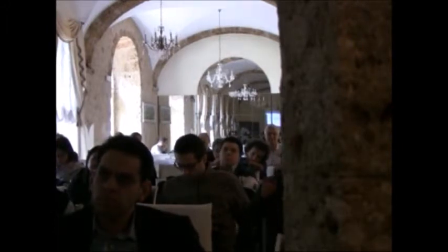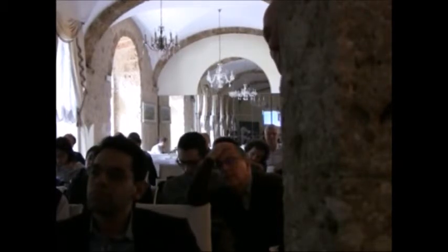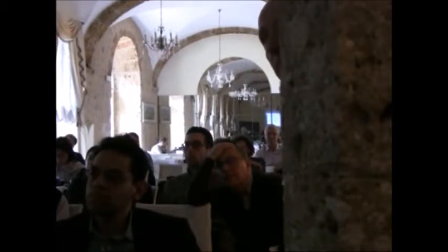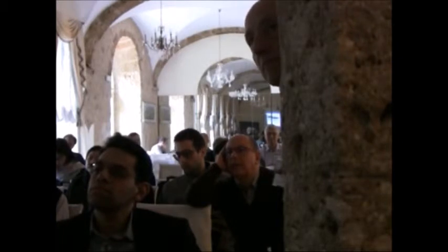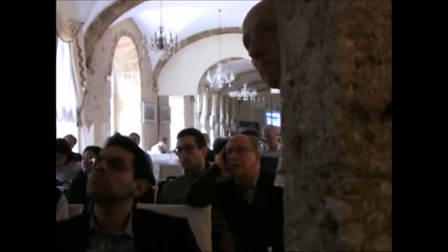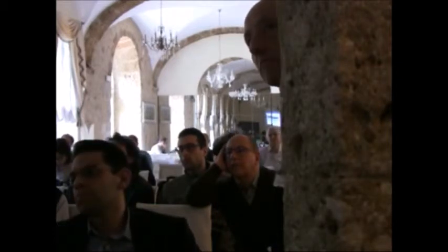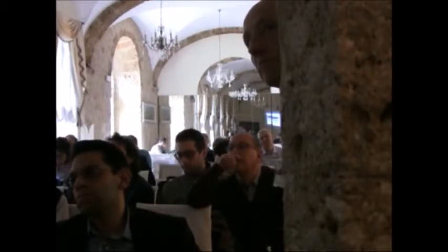I can go back to this slide. I just hope I don't take too much time from others. So, this is the undeformed state, and these gray regions are shear band gaps, and the bluish ones are for pressure, and when they intersect, it is complete. But let's ignore this. And this is already deformed by 50%. For the shear wave band gap, it just doesn't matter how much you apply. For the pressure band gap, it's just how much you want to change the thickness. This is for neo-Hookean. For a Gent material, that will be different.